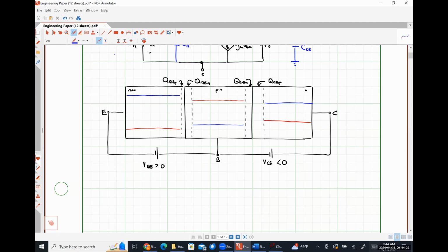So when we're looking at the base emitter junction in particular, we know that charge carriers are diffusing across that forward bias junction, and that the width of that base is very small so as to not allow too much recombination. So this is going to be drawn as if recombination is occurring, so I don't want to stretch this thing too far. But what I'm trying to illustrate is diffusion charge is being stored as well.